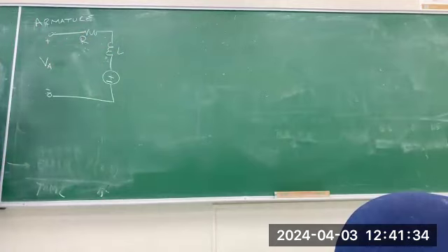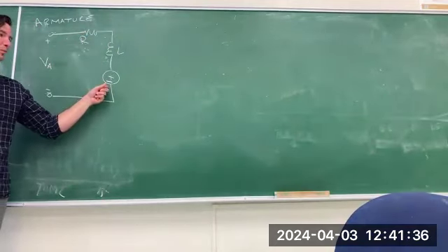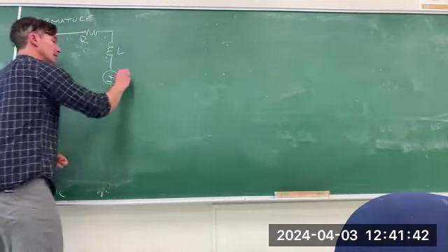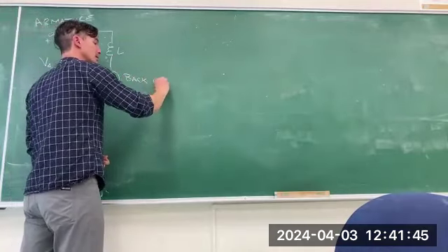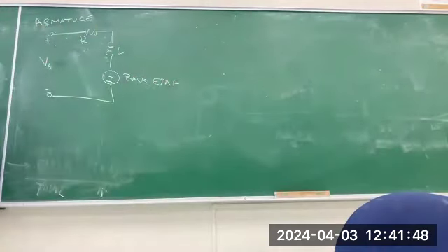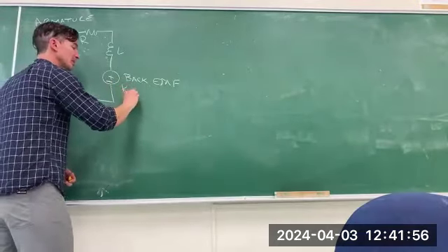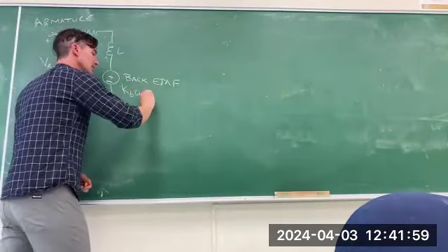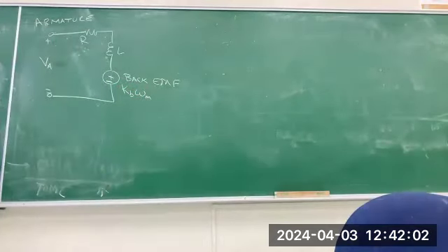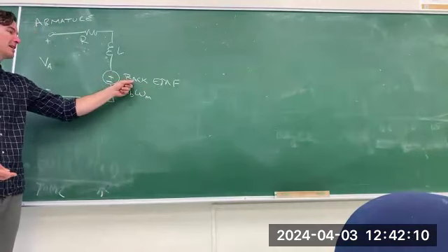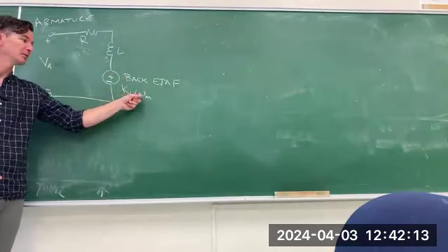And okay, here, I'll check your 255 knowledge. What is this? Good, the back EMF. Something about Faraday's law. We've got spinning magnetic fields, and the idea is that the faster the motor spins, the more back EMF is generated. EMF is an old-timey term for voltage. So I'd like to model the back EMF as being proportional to the motor speed.